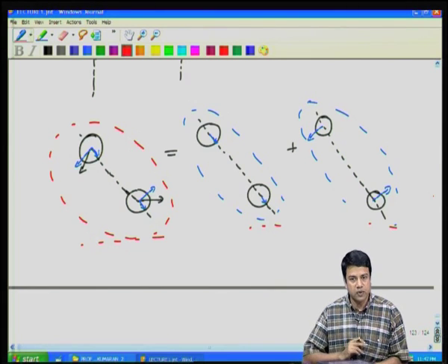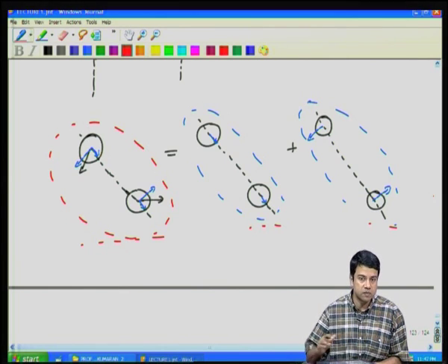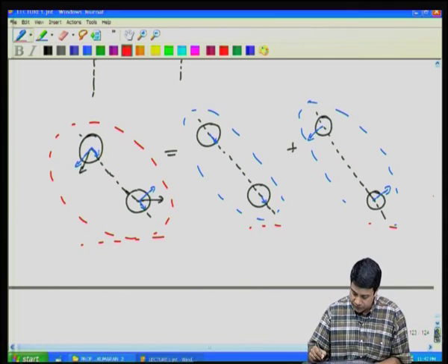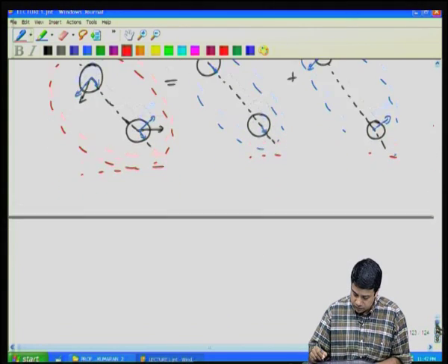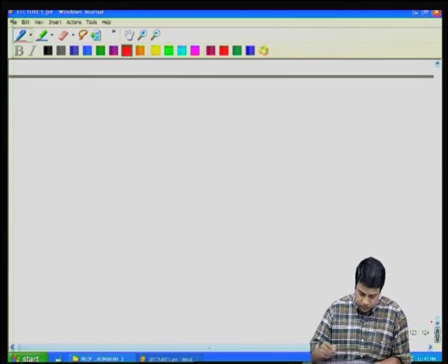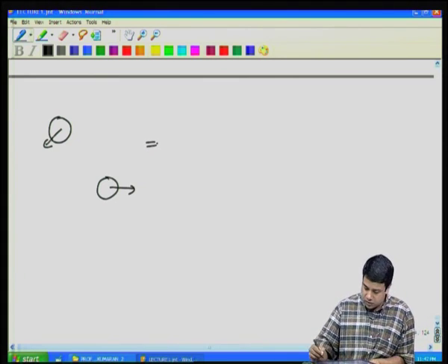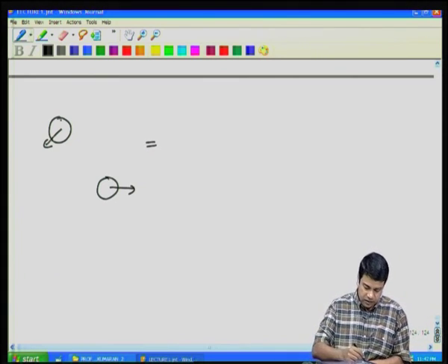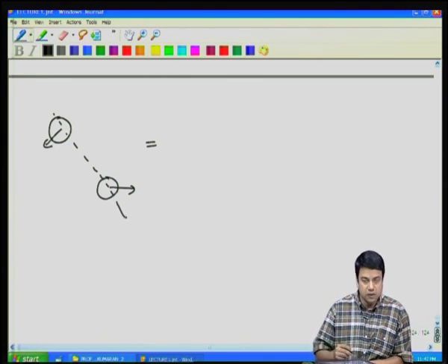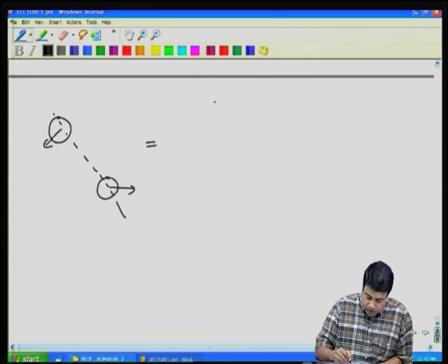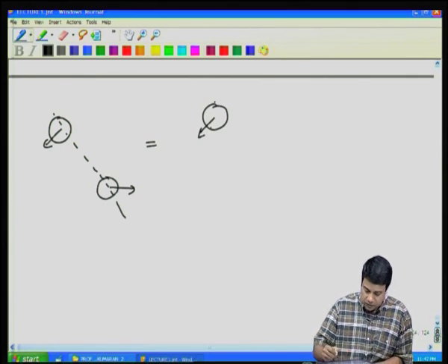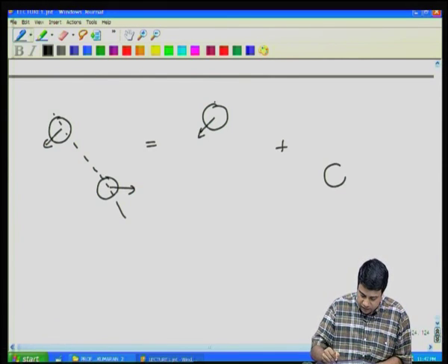An important point, when you use linear superposition, one has to be careful that the boundaries are all the same in all of those sub problems that you have divided the main problem into. Let me illustrate that. If I had a problem in which I had two objects, I just showed you that you can divide into two sub problems where you separate out the velocities into two different components. So, what I cannot do is to separate out into two problems where I retain only one sphere in one case and I retain only the second sphere in the other case.